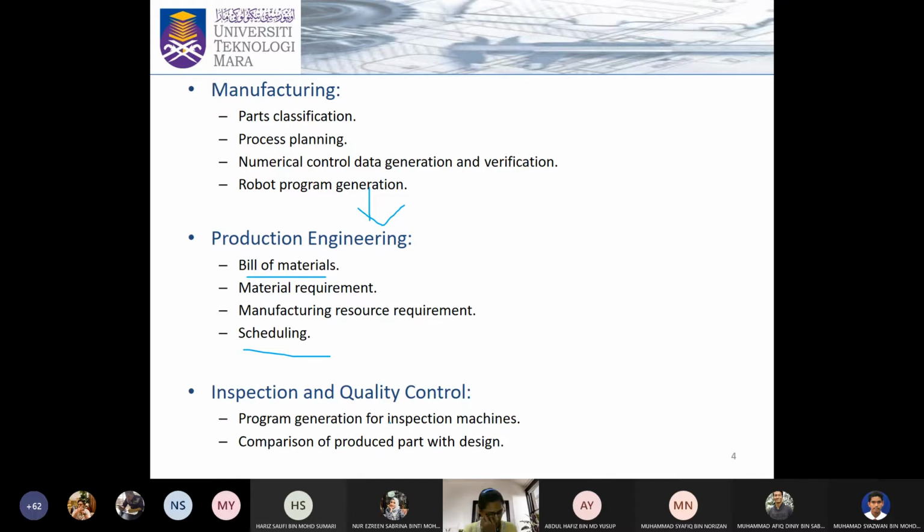So you would have seen this inspection machine, coordinate measuring machine in chapter 2, right, which inspects the quality of, for instance, the dimension of the product. So other than that, you can actually inspect not only its dimension or model itself, you may also inspect its production, right? You can have X-ray inspecting machines through augmented reality. You can also have programs where you can actually code it in such a way you can detect whether labeling has been done well, sealing, so many other things, right, can be done with your geometric model. And in the end, you can compare your produced part with the design intended.